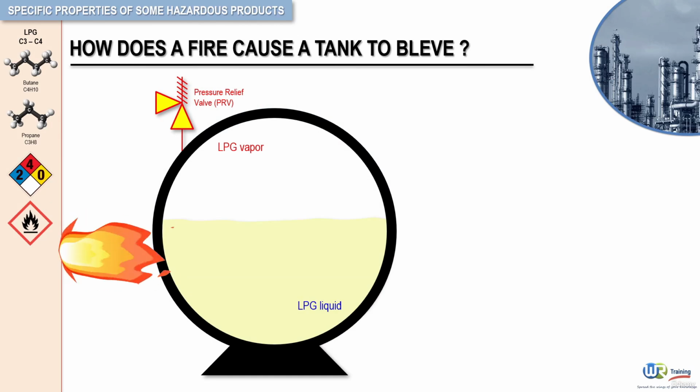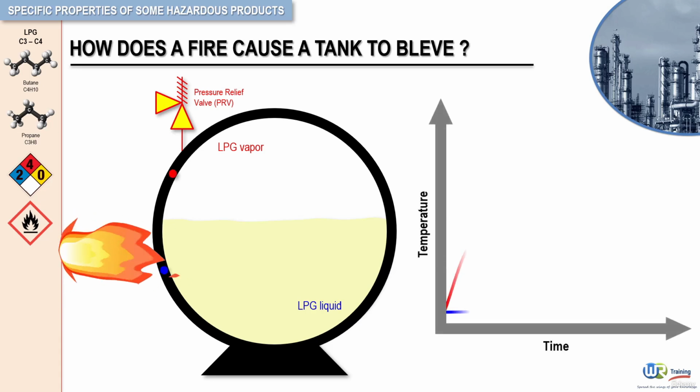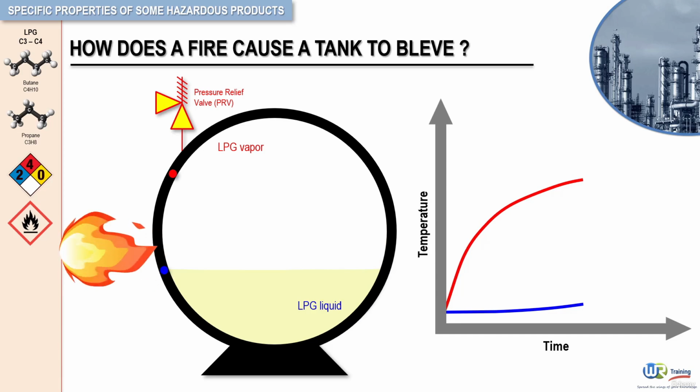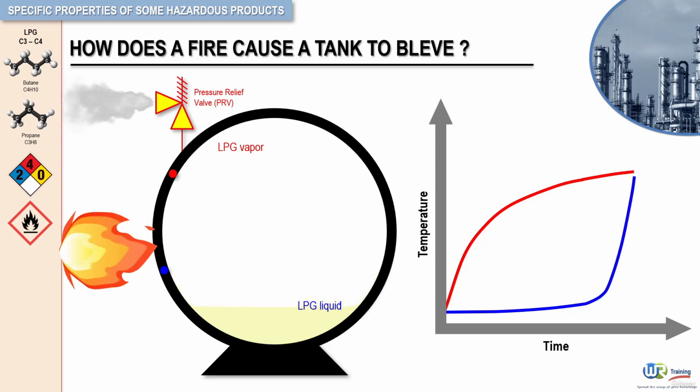The fire heats the tank walls rapidly and unevenly, driving up wall temperatures over the vapor space much faster than where the liquid is in contact with the tank shell. As the pressure relief valve cycles to reduce the pressure, gas escapes, lowering the liquid level still more and exposing more vapor area of the tank shell to the rising temperatures. As temperatures soar, the steel walls rapidly lose strength.